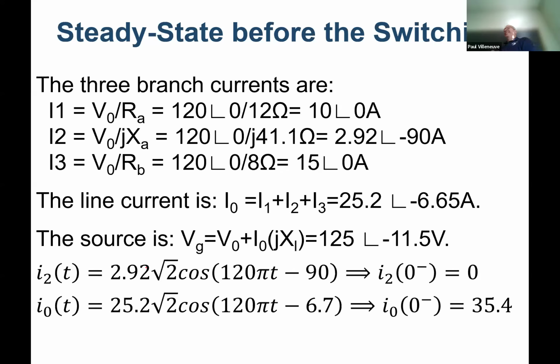I am disappointed. But in industry, when we talk about loads, we say that the load is either leading or lagging power factor. If Henry said leads and I say lag, which is correct? They're both the same, right? But he has to do it in terms of voltage, and I'm doing it in terms of current. Everybody uses lead and lag in terms of current. So if he says it's leading, then I would say, hey, the current's leading the voltage. Is that right in an inductive circuit? No, it would not be. So we all have to be on the same page, which means what is current doing? Current has to lead or lag. Remember that?